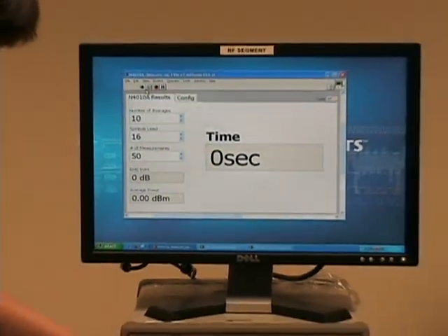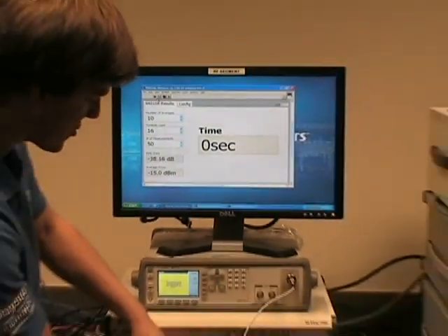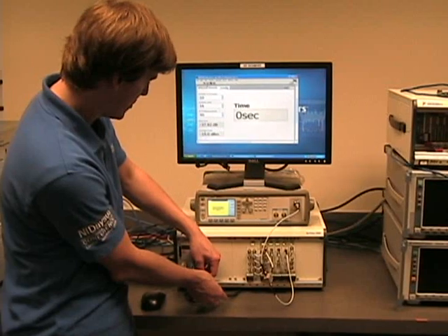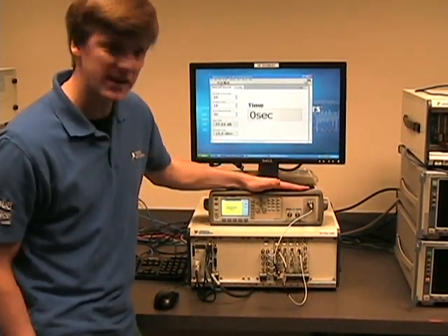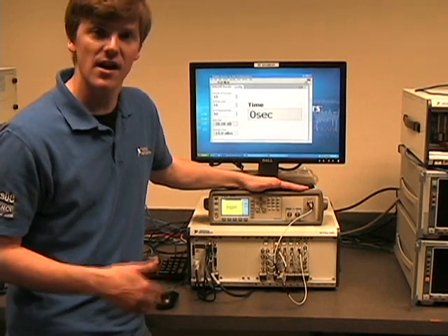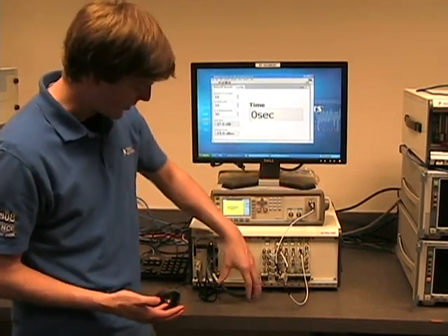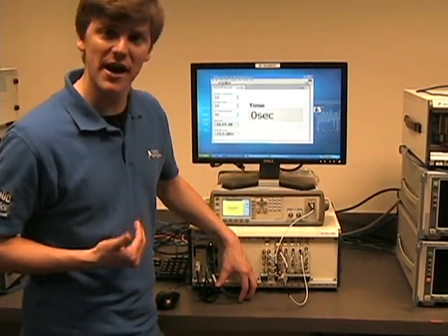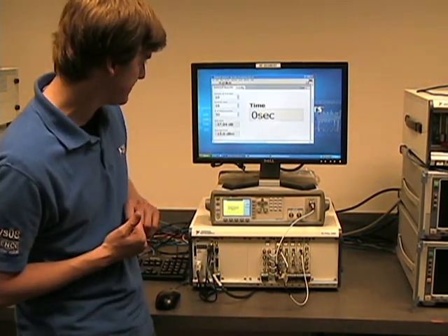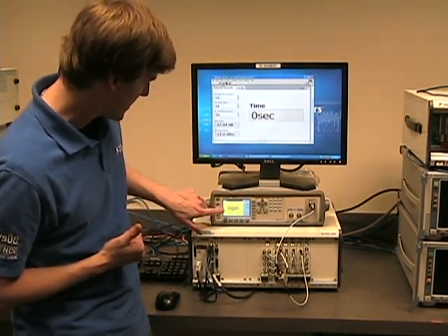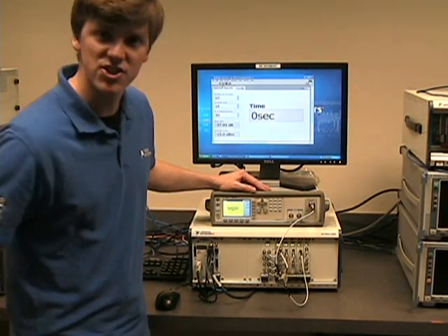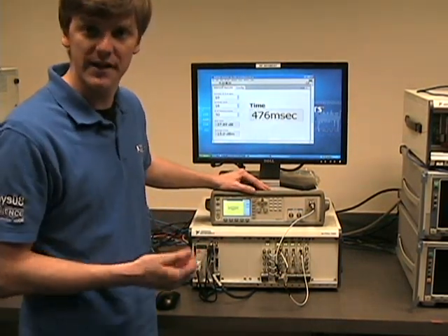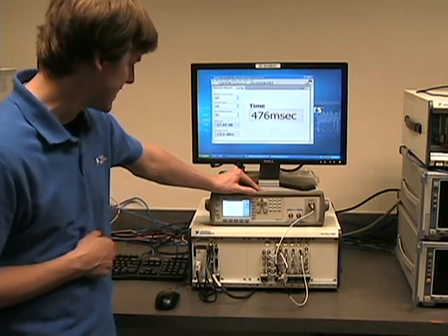As you can see, the test system I'm using is actually controlling the N4010A through a GPIB cable. We're using GPIB in this case because it has the lowest latency bus versus LAN and USB, and will add the smallest amount of overhead to total measurement time. And you can see it's running the measurement. The front panel of my N4010 says that this instrument is currently being remotely operated, and of course it's being controlled by the PXI instrument.